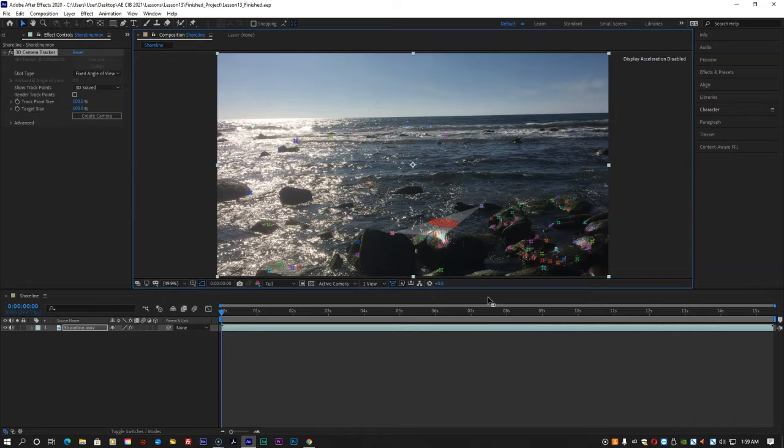The ground plane and origin provide a reference point, setting a point where the coordinates are 0, 0, 0. Though nothing appears to change in the Composition panel using the active camera view, the ground plane and origin make it easier to change the camera's rotation and position. Right-click on Windows or Control-click on a Mac on the same plane and choose Create Text and Camera.